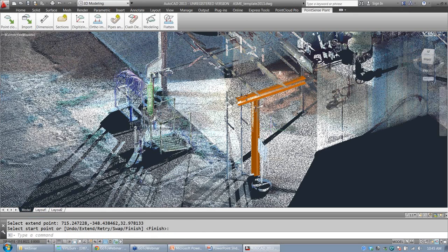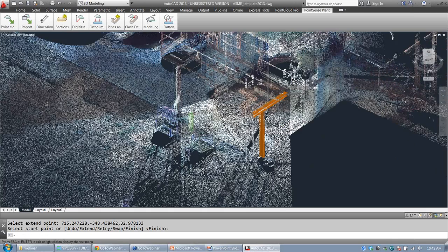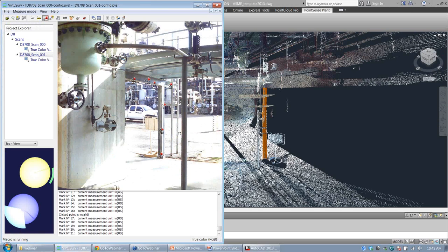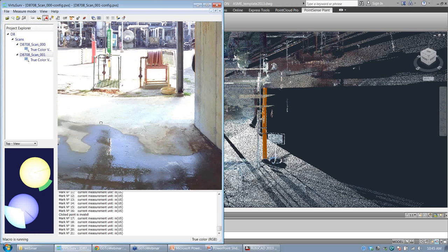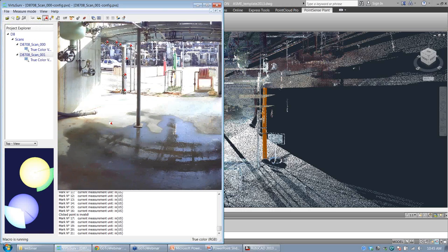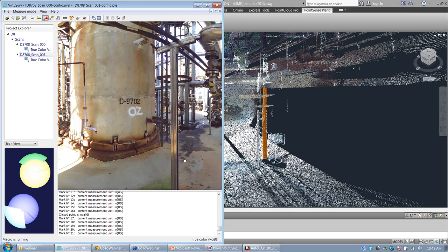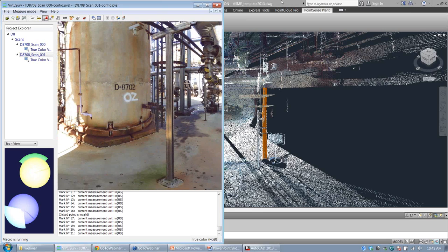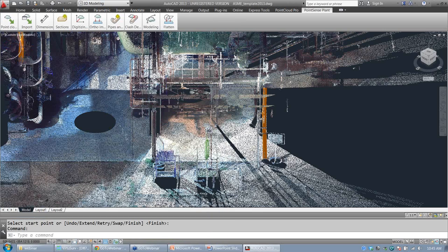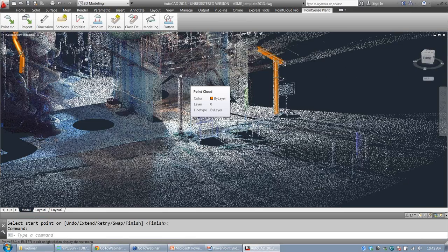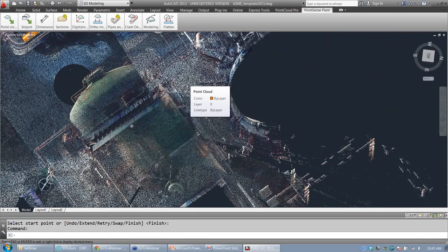So that's the steel fitting, and actually you'll notice the custom profile fitting is very similar. And for the example, I just went and used a little piece, 1 second, right here, because this is not in the catalog. So really what I did is I drew a polyline, and let me just turn off this cloud so I can see it.